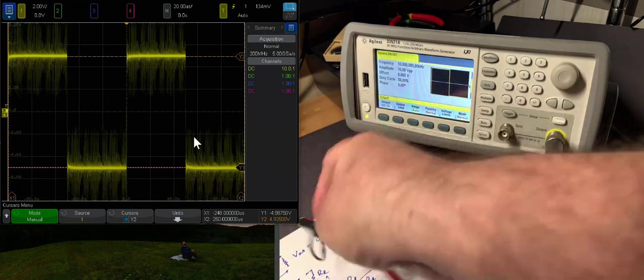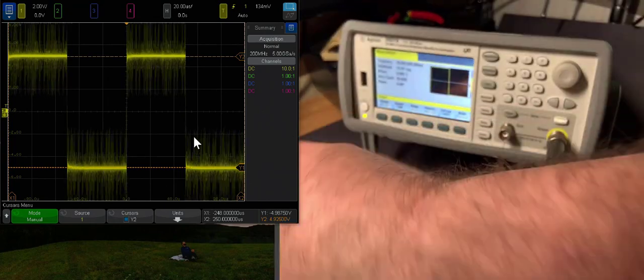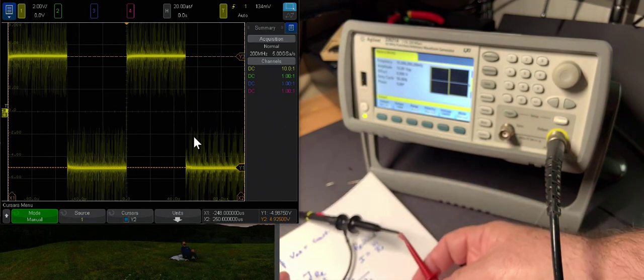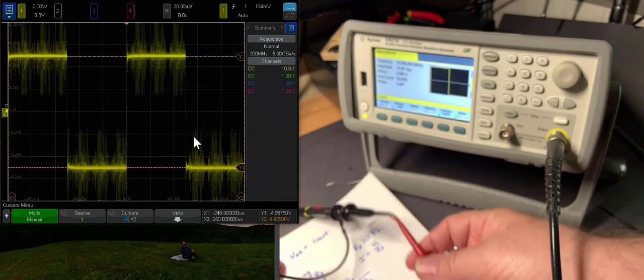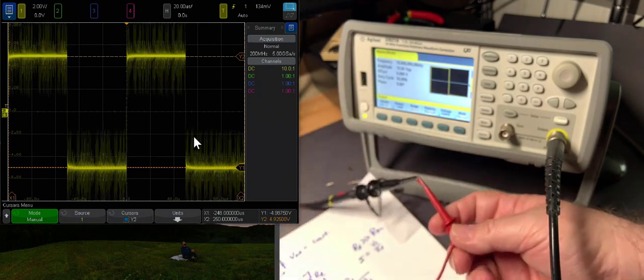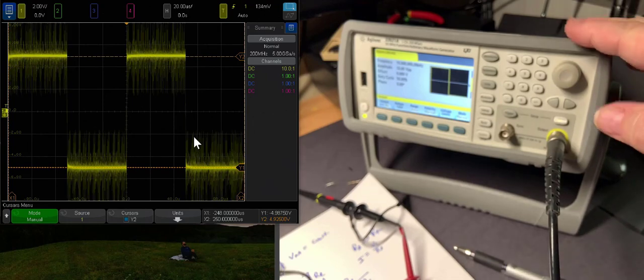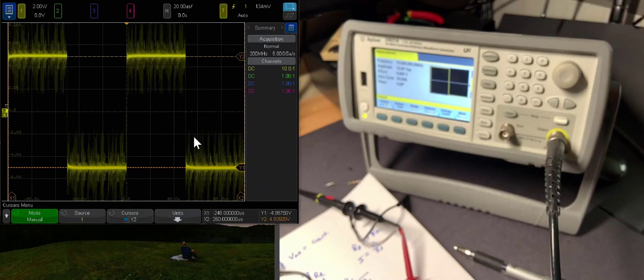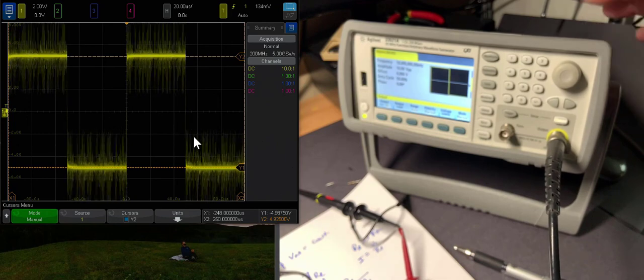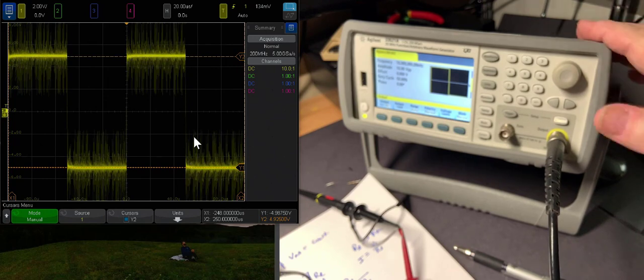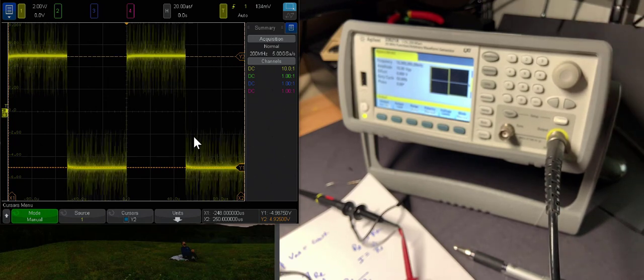You say, well, wait a minute, how is it possible to get a voltage measurement on the signal? We still get that roughly plus or minus 5-volt signal. How is it possible to get that 5-volt signal if we don't have a ground connection? They're disconnected. And that's because the function generator is plugged into the power strip. The earth ground is connected to the chassis ground, and the chassis ground is connected over here of the function generator, and exactly the same thing in the scope.